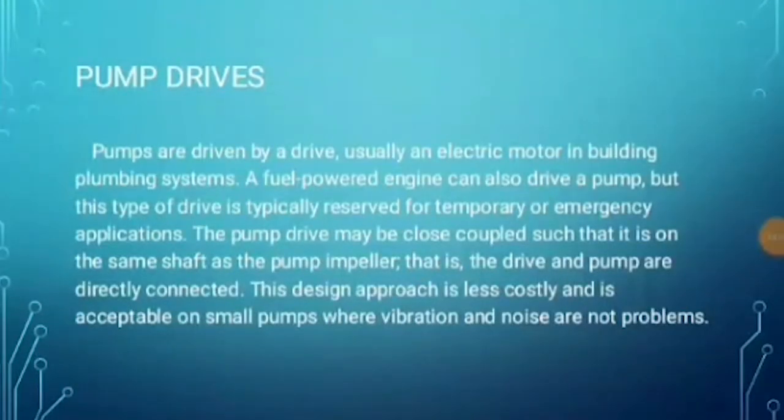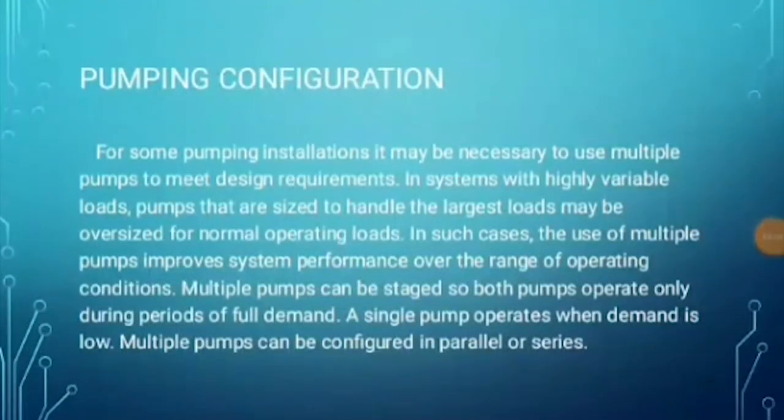Pump drives. Pumps are driven by a drive. It usually consists of an electric motor or a fuel-generated engine. A fuel-generated engine is temporarily used for emergency applications. Pumping configuration. In heavy loaded buildings, installing several pumps either in series or parallel is necessary. Using this strategy, the pressure can be increased and water can be distributed all throughout the building.